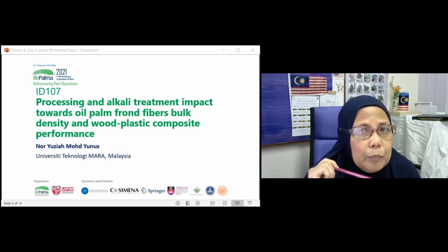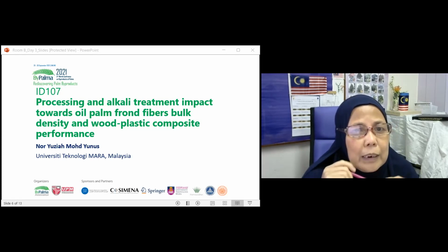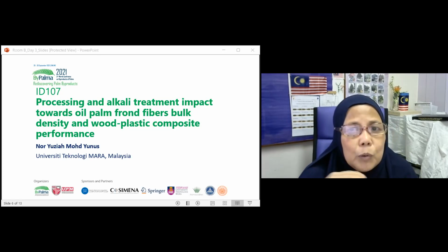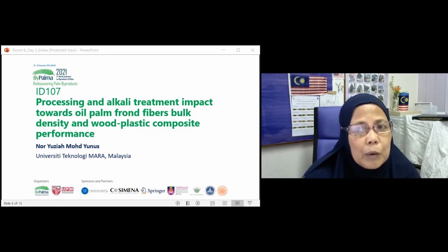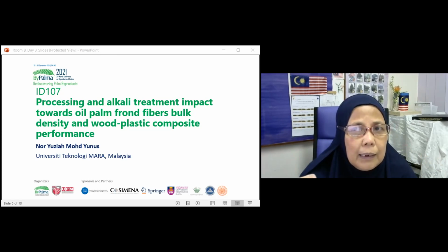So if the melt flow index of your plastic is too low, you might have a problem. That is if you want to do what we call conventional blending, which means you are not going to do any irradiation. But if you want to do radiation together, which is what I have done, you should use something like between 5 to 7 melt flow index. The reason is that the moment you hit it with electron beam, it will drop the melt flow index. So it depends on what you want to use it for.